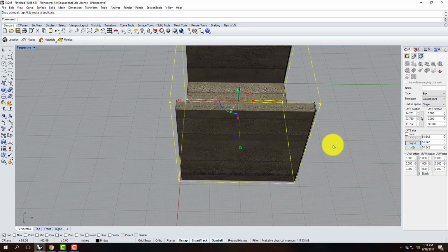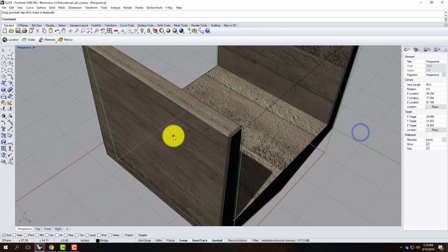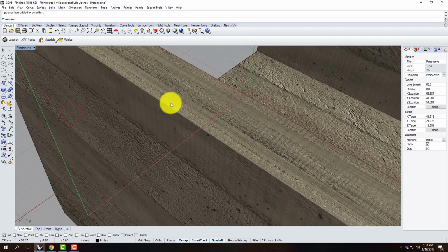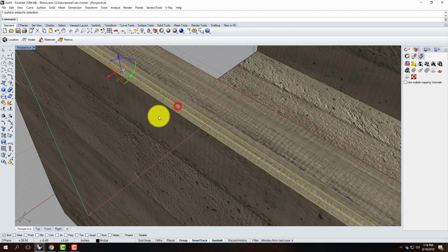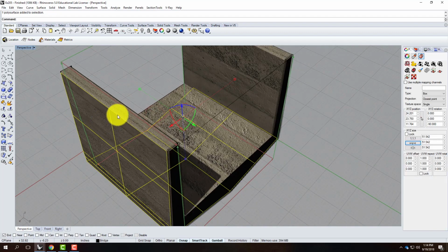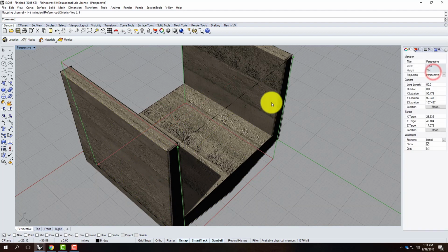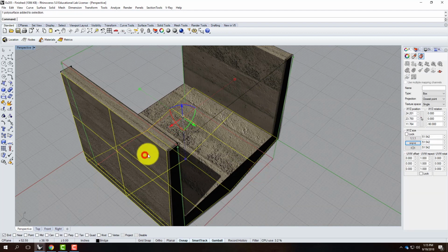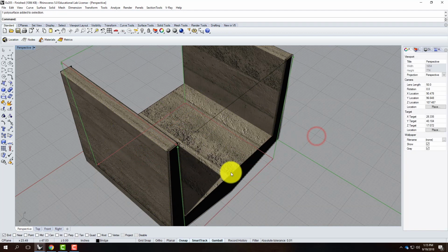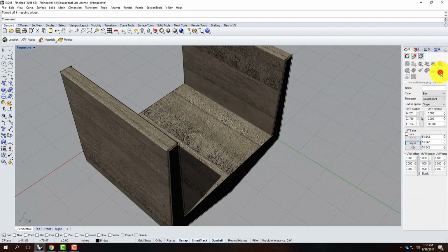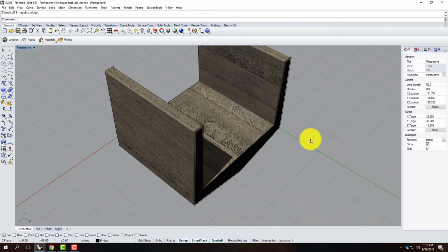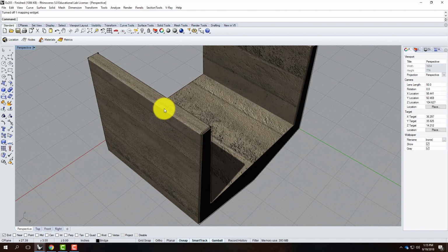So I spent all this time and work, and I got that texture mapped correctly, but I missed these other objects. And this is where I said you could just do it all at once by selecting them, and I would do that typically. The good news about texture mapping is you can copy your mapping from one object to another object. Let me go ahead and hide the mapping widget there. Good. And so I can change the texture mapping on another object.